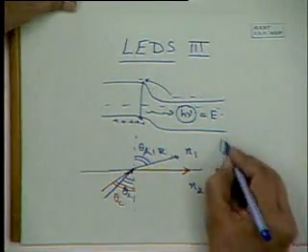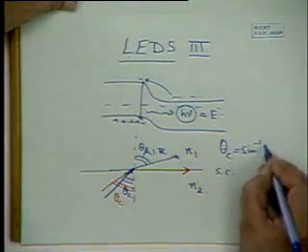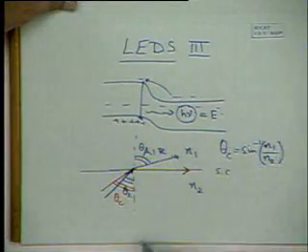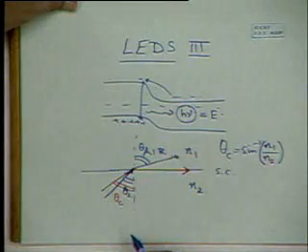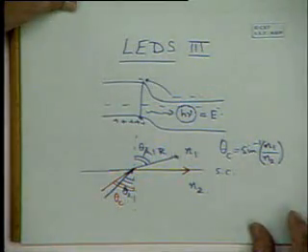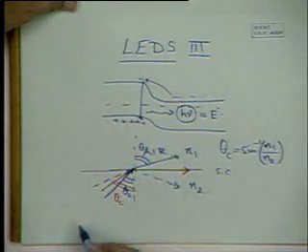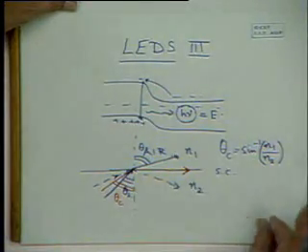The critical angle theta c is given by sine inverse N1 by N2. And since N2 is large, this theta c, the critical angle, is rather small. Beyond this critical angle, we know that light will be totally internally reflected. So this is a problem with semiconductors, because N2 is quite large, of the order of 3, and if we look at typical semiconductors like gallium arsenide or gallium phosphide,